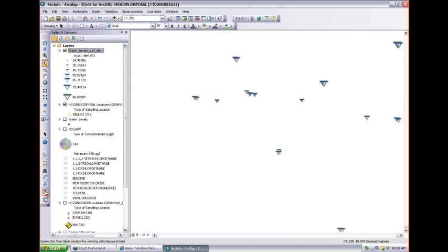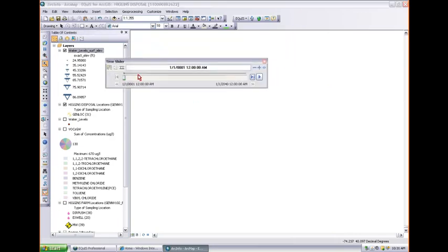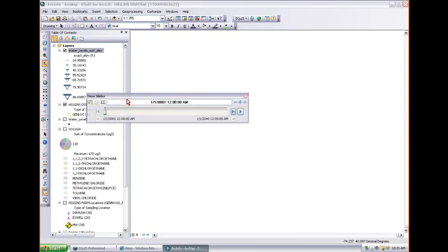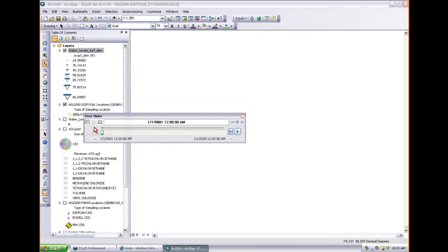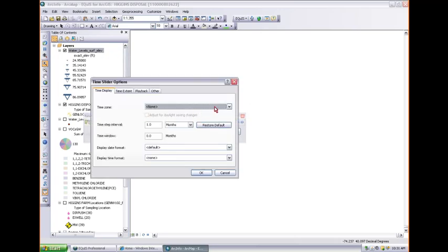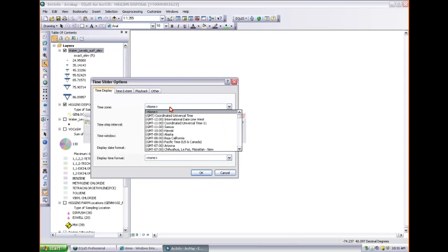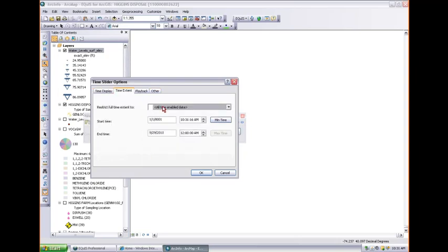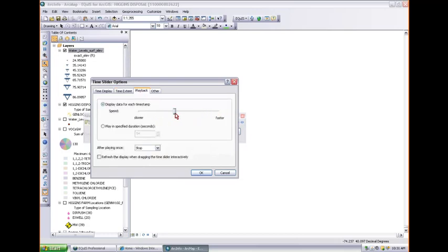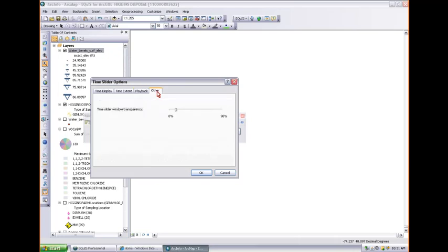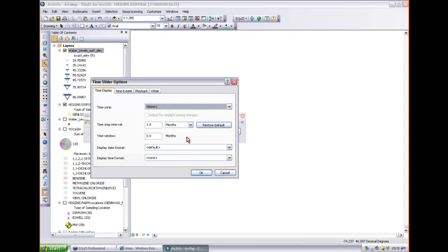So when you do this one layer for all your dates, this is another ArcGIS 10 feature, time-aware layers. We can use this feature to show a snapshot or animation of any layer over time. We set up the time slider intervals based on a layer, which will be this water level. Just like the Surfer, you see they borrowed here from Google Earth. It looks almost exactly the same as their slider. So we'll use 2006 to 2010. Does that sound about right for our water level data? It'll use the min-max by default.